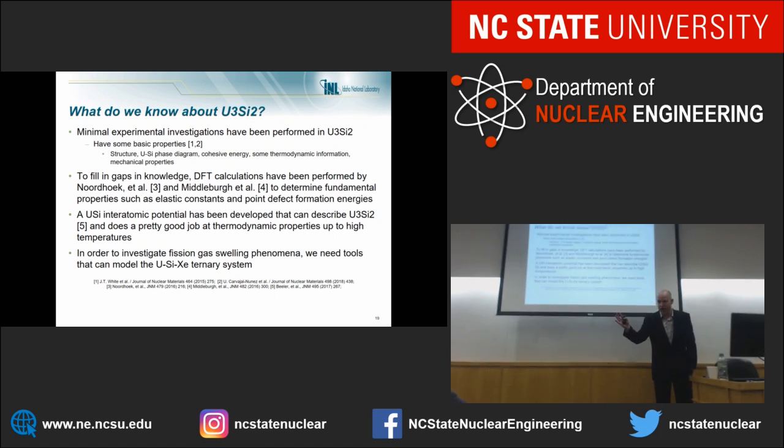But to fill in some of the gaps, we've worked with people at Los Alamos to do some fundamental density functional theory work to determine a lot of the elastic constants of this system and a lot of the point defect formation energies as well. Where I had a role is I took the density functional theory data from Los Alamos, and I was able to make an interatomic potential to describe the uranium silicide system.